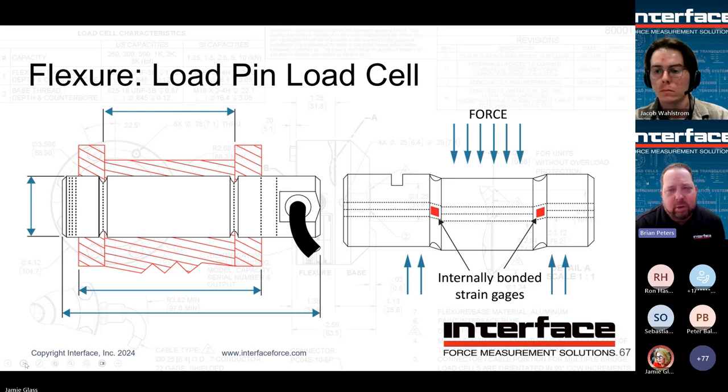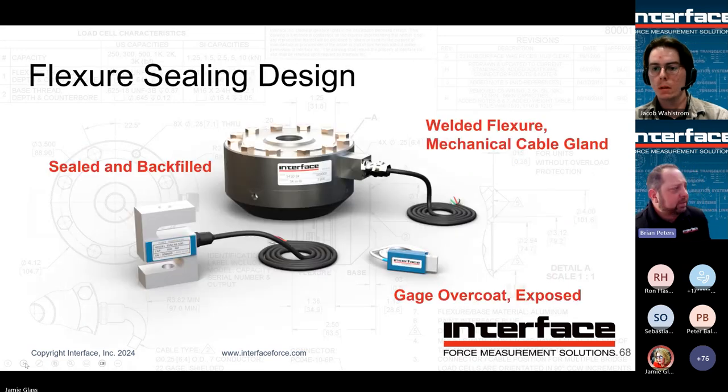So as you push or pull that middle section up or down, you want to make sure that the stress concentration areas depicted by the grooves, again, if you reflect back to some of those other flexures where we neck down the material so that we can maximize strain. Same thing going on here. The gauges are going to be directly under those grooves, but that's where you want to have that double shear interface occurring from a system level standpoint. So it's really important you have tight tolerance, that you keep the pins in shear, and that you don't bend the load pins. So, all right, next.